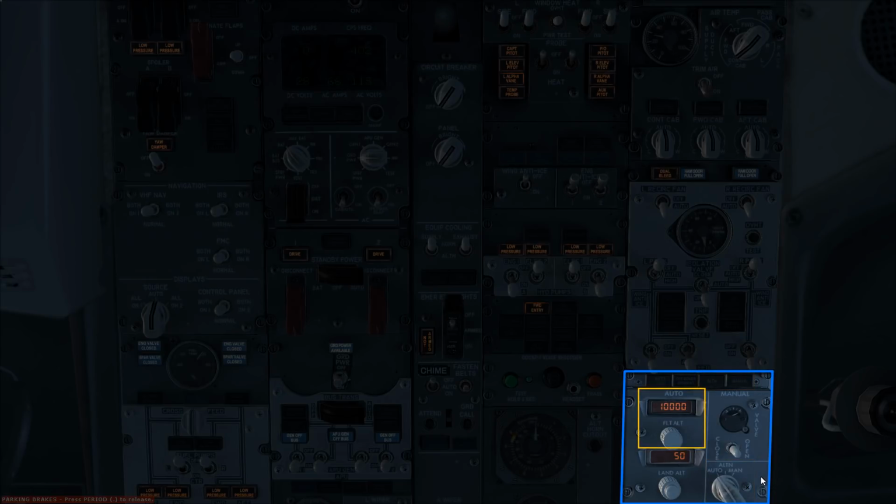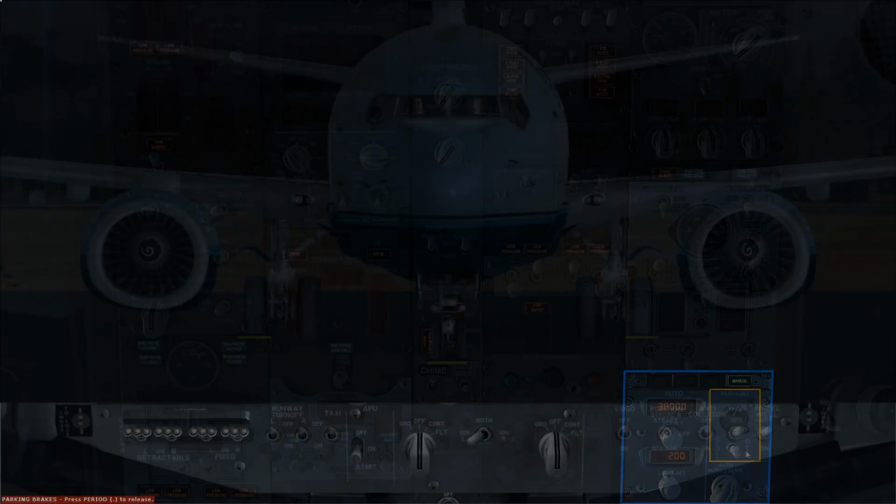This here is your flight altitude selector, so you would dial in your cruising altitude before the flight, so the automatic system can control cabin pressure accordingly. Below that you also have the landing altitude selector, again so the automatic system can calculate how to manage the cabin pressure. On the right we have a little indicator for something called the outflow valve, which allows air inside the cabin to escape. This helps to regulate air pressure inside the cabin and is automatically controlled by the pressurization computers. However, in the event that pilots are manually controlling air pressure, they can open and close this outflow valve using this switch.